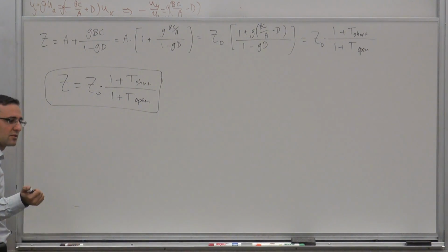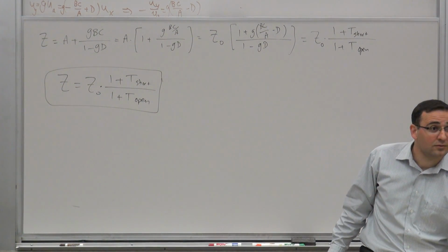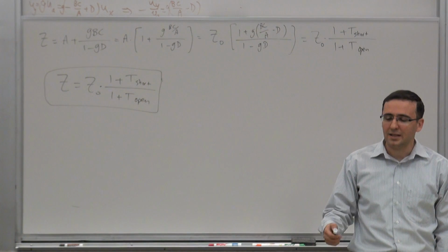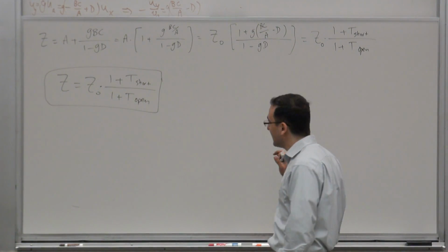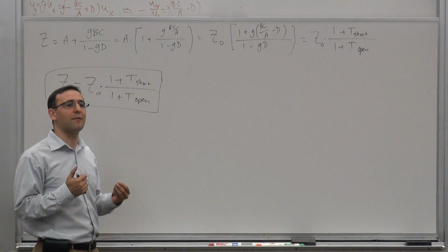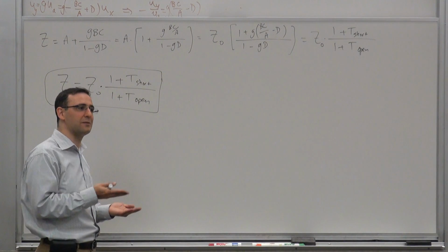And that gives you the impedance. So, alright, so much for discussion. This is independent of the choice of the dependent source, right? This is again independent of the choice of the source. It's valid for all sources, but again, for it to have physical meaning, you want to pick sources that are relevant to the feedback system.